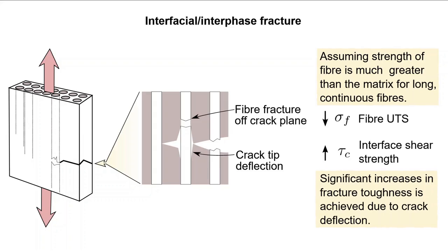To get the best return from this phenomenon in terms of a higher fracture toughness, a relatively lower strength fiber with a relatively strong interfacial strength is the best route. The improvement to the overall fracture toughness is that the crack has to deflect off of a plane where the stress concentration is highest. But it also adds a whole lot of new surface area to the crack flanks. This additional surface area associated with the crack can also be realized for shorter, less continuous fibers as well.